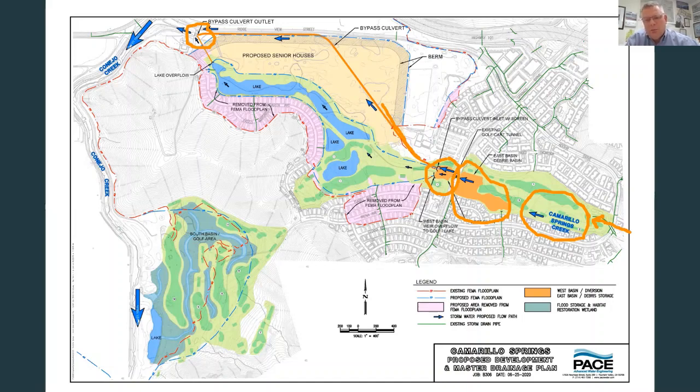And so by having this large storage area upstream of the Camarillo Springs Drive, we have significant storage. We eliminate any potential for debris, sediment, large branches and trees, and anything that can come down off the mountains that would get to the golf course area. It can't get to the splitting basin here.